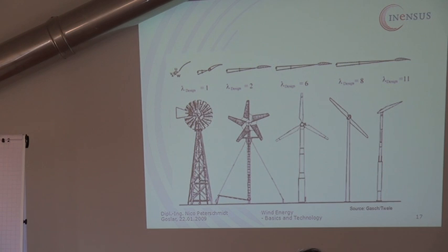If you want to generate electricity, it makes much sense to have quite high rotational speeds, because this is how you can decrease the size of your generator. Otherwise you will need a gearbox, or a large gearbox, with several steps. Therefore the turbines you see here, with 3 blades, have 3 blades because in that case the efficiency is quite good, the tip speed ratio is quite good, and rotational speed at nominal wind speed is quite high.